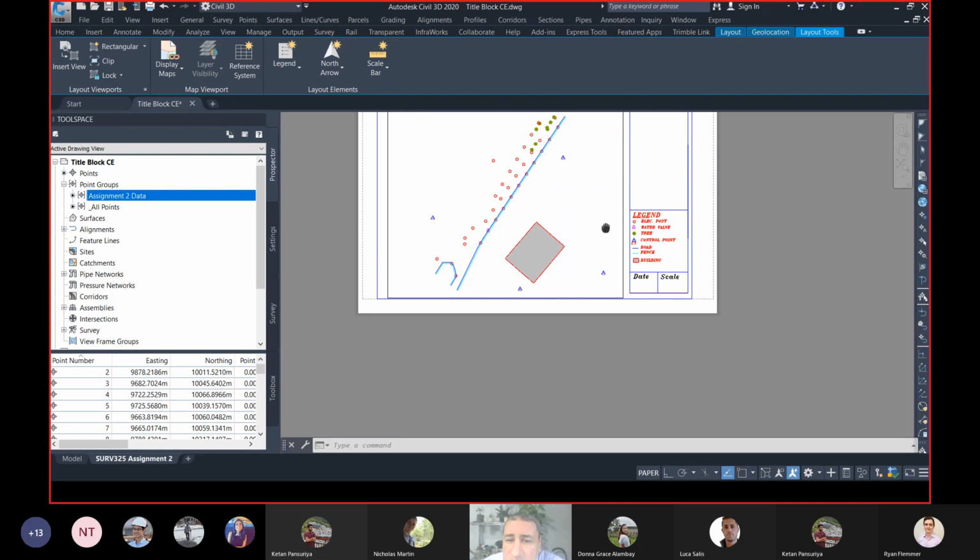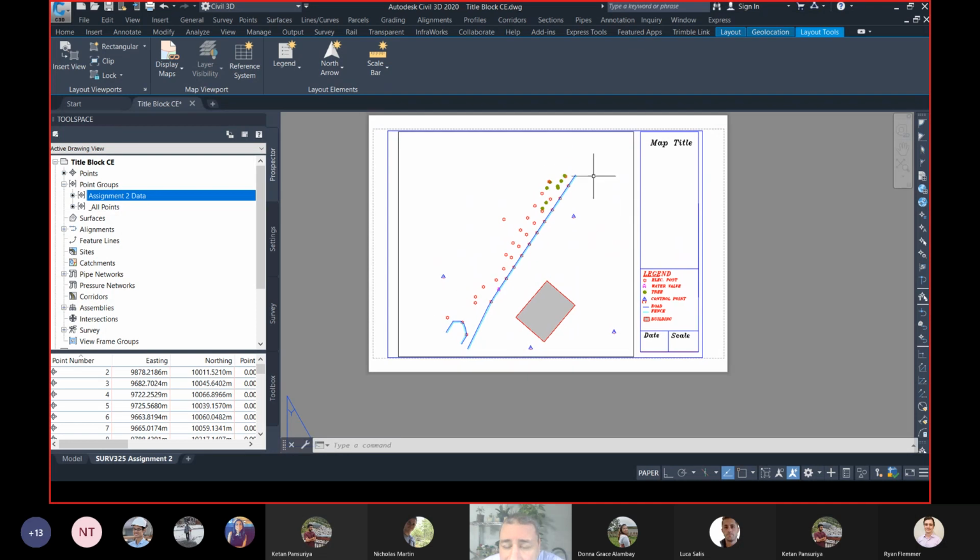In general, guys, look at this. The scale depends on the size of the area that you have done, and also it depends on the size of the paper. A couple of things determine what the scale should be. For example, this area is 500 by 500 meters, and I want to present this 500 by 500 on an A3 or A4 or A0. Remember, those standard paper sizes have a size in millimeters. So this is scale. I have done this effort on your behalf.